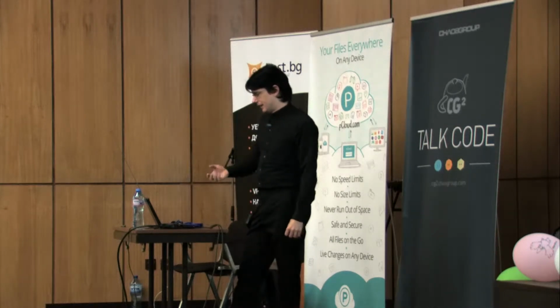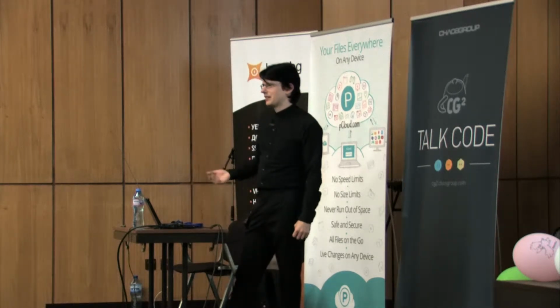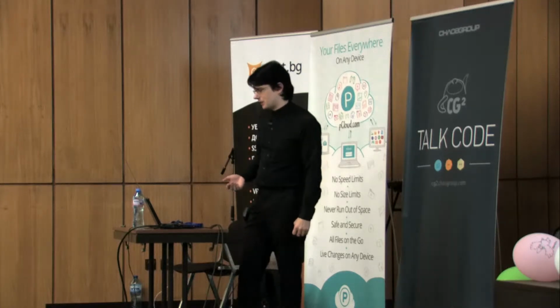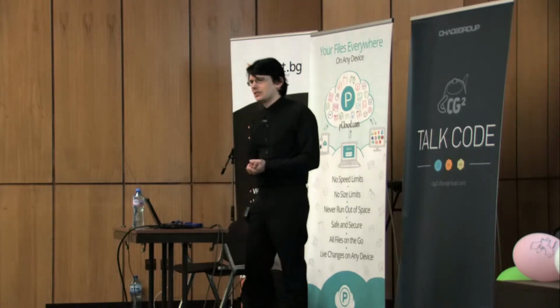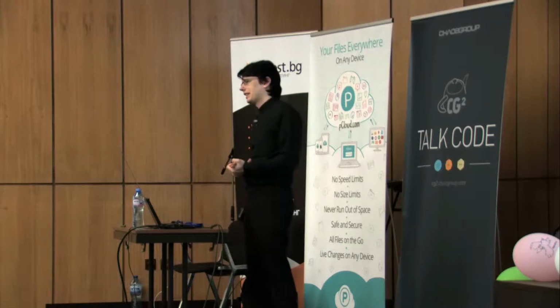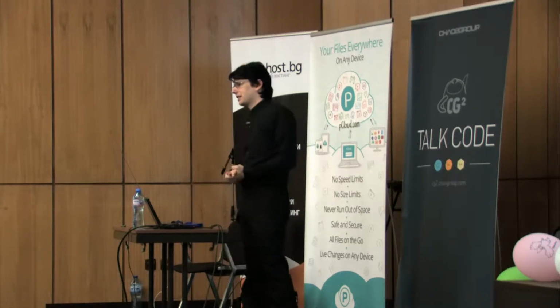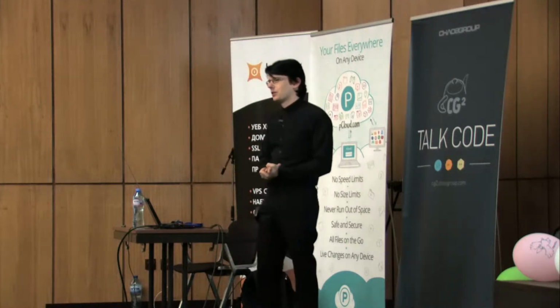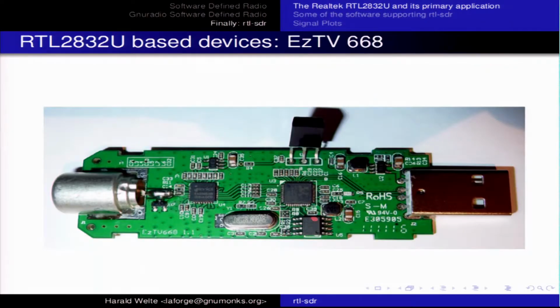Now, after some protocol tracing, this basically was figured out, and a project called RTL SDR was created, which is an open source project that basically talks to this Realtek chip. It activates this special mode for forwarding all the raw samples, and it consumes those samples and makes them available to various applications that may be interested in those samples.